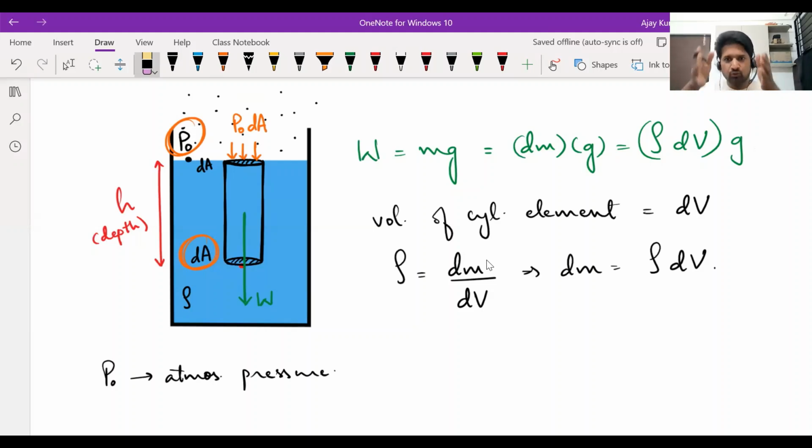See, this volume is surrounded by liquid, right? Now imagine if we make a hole in the container here, liquid will flow out from there. That means liquid is pushing the wall of the container, right? Wherever the liquid is in contact with something, it will be pushing it. So the liquid here is pushing the wall of the container. Similarly, the liquid surrounding this cylindrical volume will be pushing this cylinder inwards, exerting a force inwards on this cylinder like this. From below also, there will be forces acting. So from all sides, there will be forces acting on this cylindrical volume perpendicular to its walls. Surrounding liquid will be exerting this force.